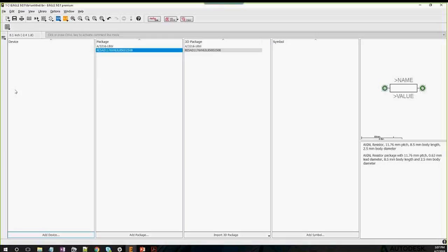How do you generate STEP files for people who do not have Fusion 360? So that's through Fusion Team. You need to be able to access Fusion Team. And then there's the option to export your design data in a whole bunch of formats. STEP files, I think there's SolidWorks files as well, and a few others. But it requires having access to Fusion Team. So if you don't want to use Fusion 360, you would still need to get Fusion Team.